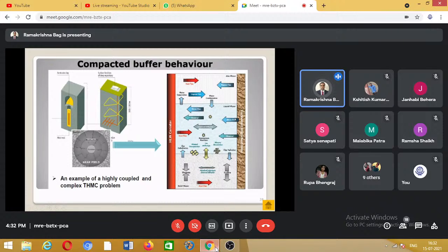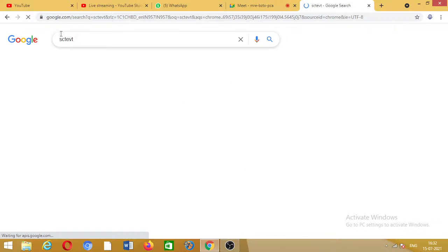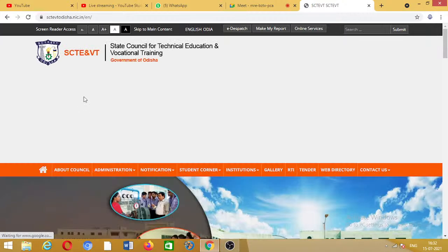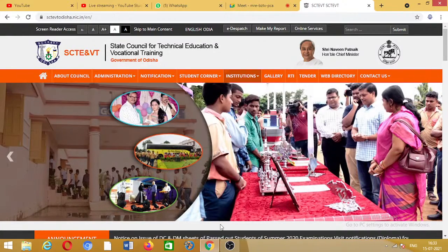So what are the things we need to look at? The swelling pressure which is developing; any change in chemical properties due to the flux of water; how the saturation inside the blocks is affected; and how much time it takes for temperature to flow from here to here, which depends on the thermal conductivity. That also depends on the water content.